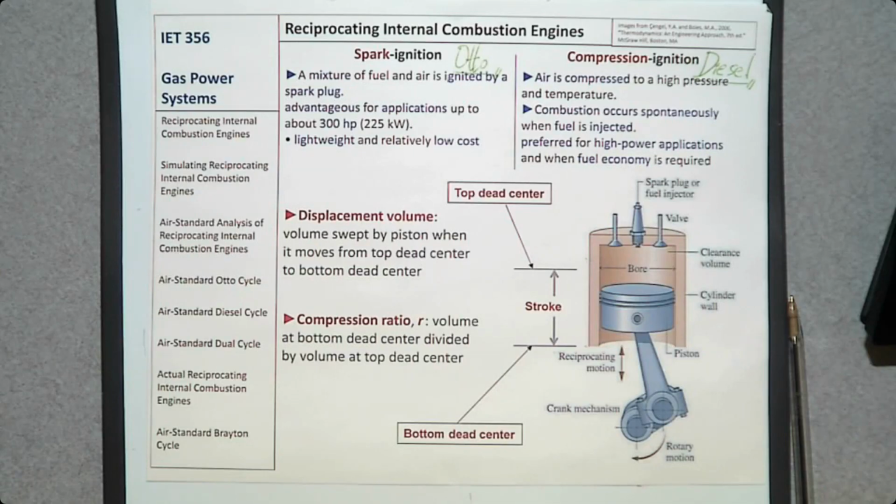But one thing that you can think of is, if you have a combustion within this volume, what about if you have the same combustion within a much smaller volume? Which one will create more power? When you make it as small as possible and let them ignite, the power produced by the combustion is going to be much greater, right? So ideally, we want to compress this air-fuel mixture as much as we can. In other words, we want to increase the compression ratio.